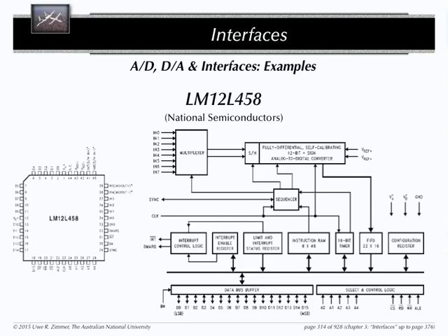This bus interface has a number of wires which you can then use. This is 16-bit. Those, in fact, go directly on your CPU bus. So you can take the soldering iron and wire those 16 bits onto your CPU bus. I have a few more. You have 5 address lines which go into that thing.